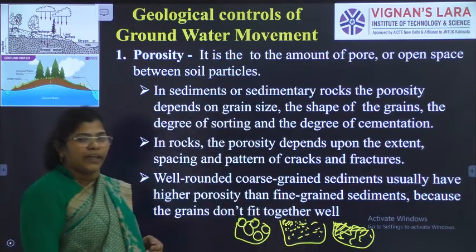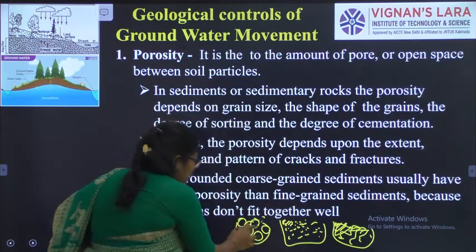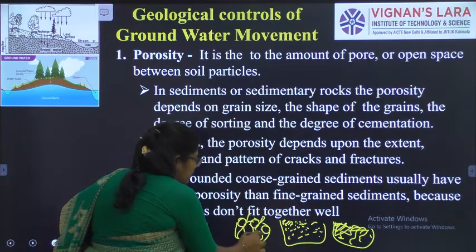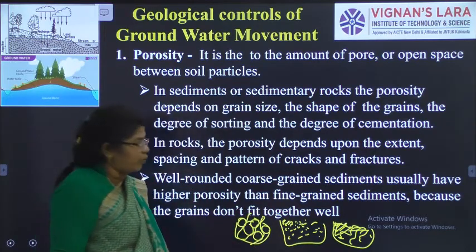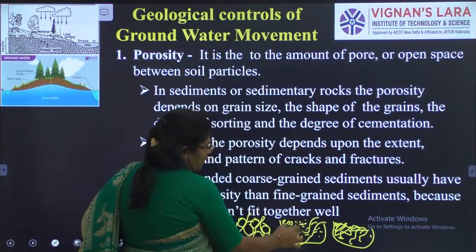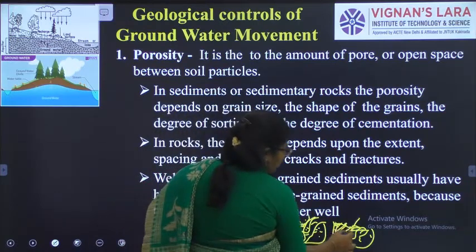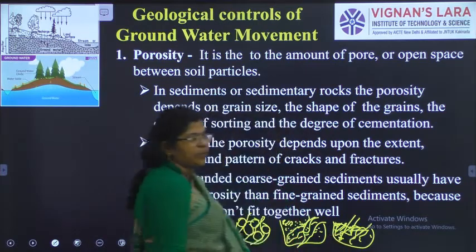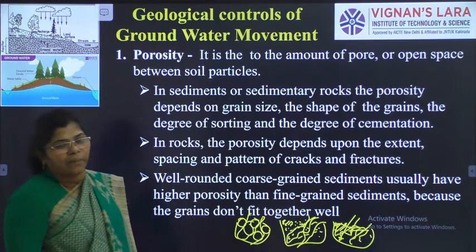Water will flow very high through the gravel because there are so many zones through which it can easily flow. In sand it will also flow, following the gaps where they are. But in compacted soil there is no continuity of pores, so flow won't happen there.